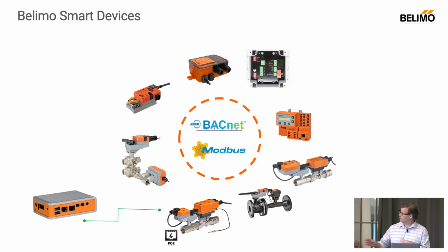We have that one, I guess the 10 o'clock position, is a VAV compact. This is our airflow measurement and control actuator. Next over is our VRU. So same guts as the VAV, but it allows you to hook it up to a different damper. So if you need a larger torque range, you hook it up.